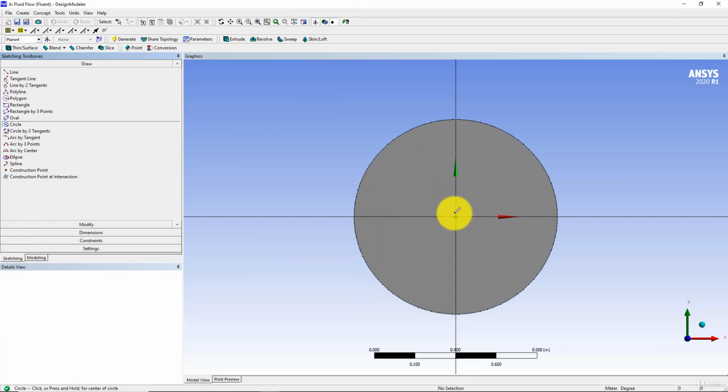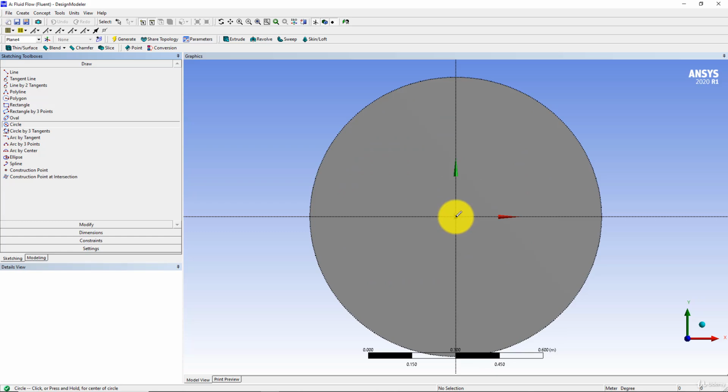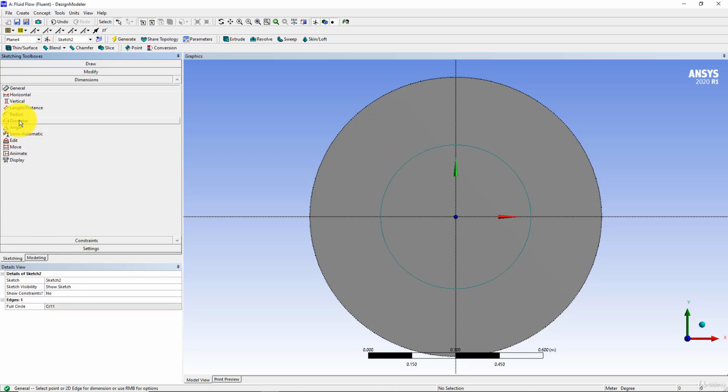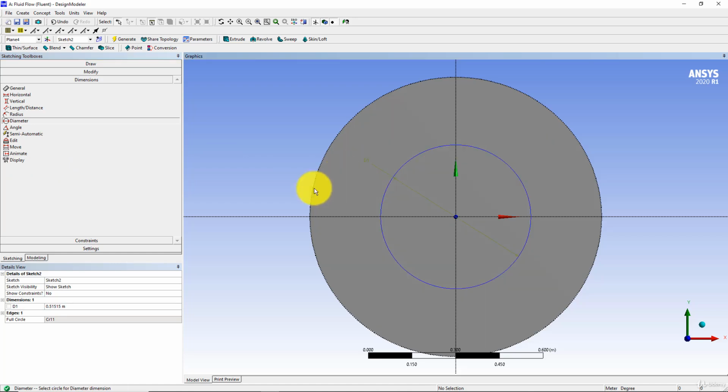And now choose this Plane 4 and Look At sign, and go to sketching mode, and from here again on this origin point, and drop this circle anywhere, but it should be inside this larger circle here, and put dimensions from diameter and put the value as 0.5. And later on we will be making the parametric dimensions of the larger pipe. You will see how this can be done.